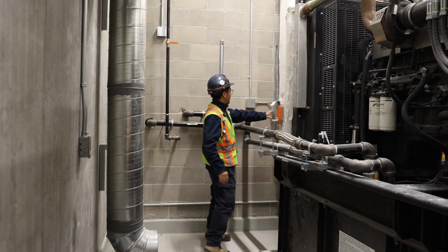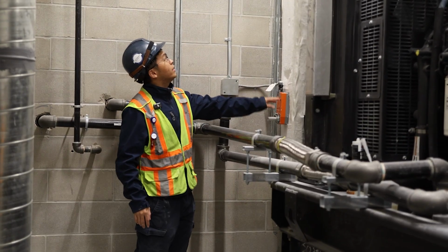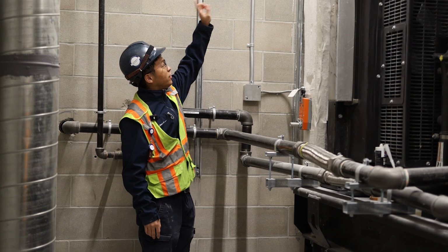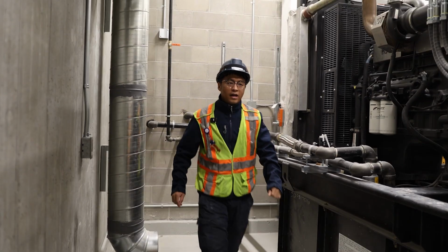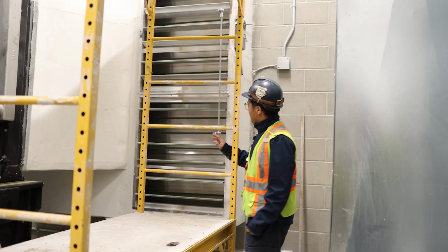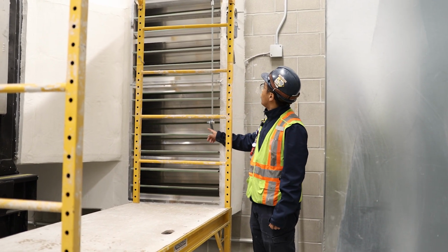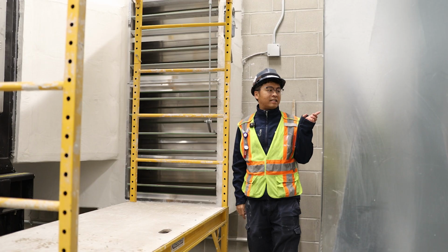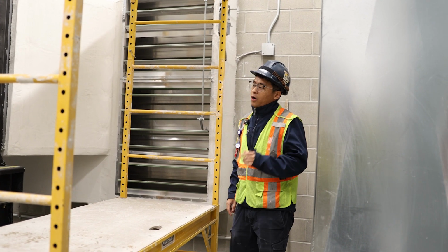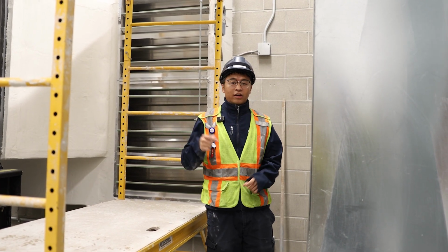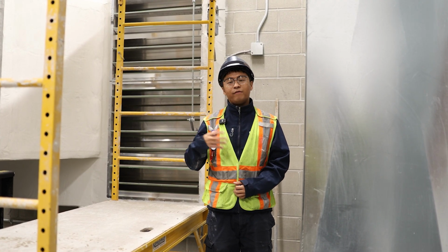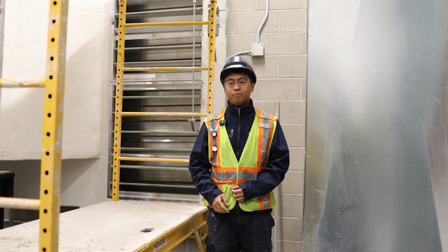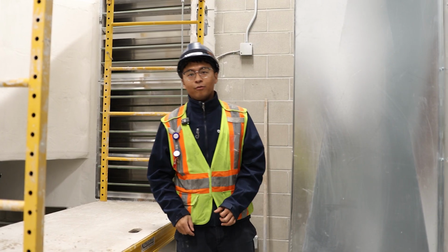And this is our relief air damper actuator. That's also an exhaust air damper. Those two are the exhaust air dampers. And we also have, this is the recirc air damper, and this is our outside air damper. So whenever the generator starts, those dampers will start opening to modulate the space temperature to provide the cooling in the room. I think that's everything in the generator room.